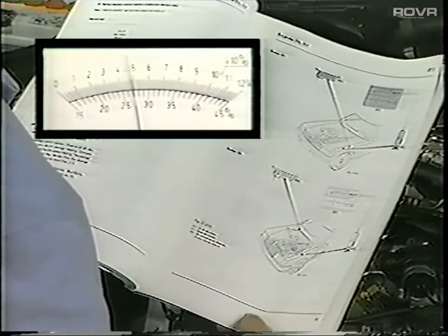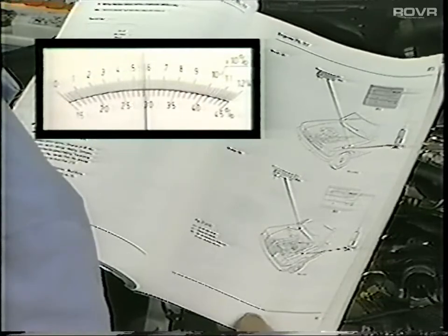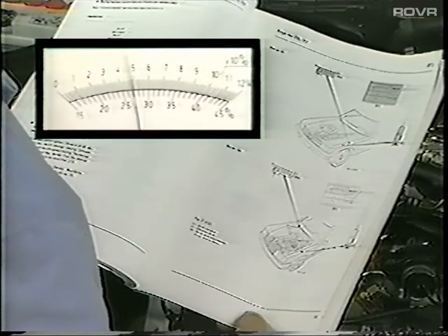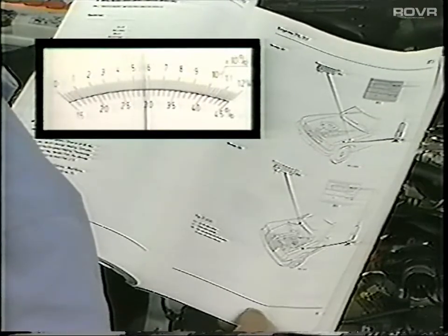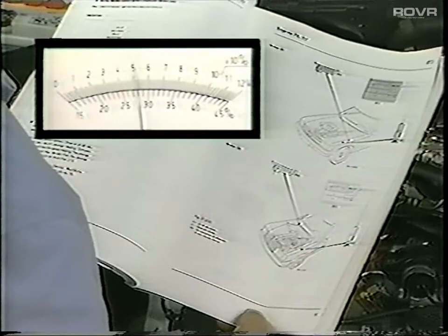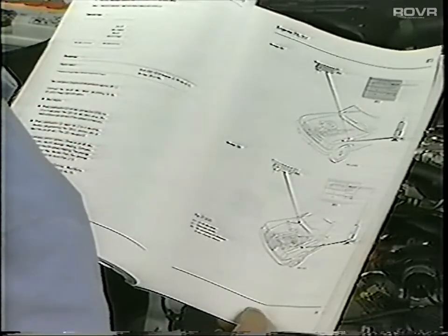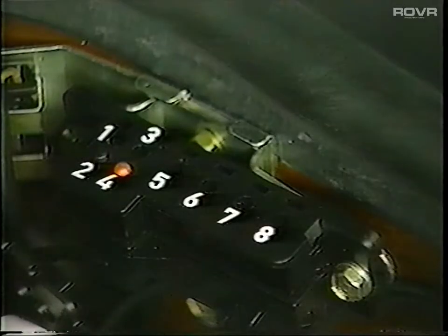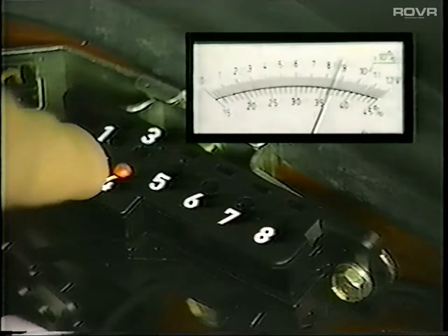The information in Test B is important since it explains the procedure now necessary to cancel the diagnostic signal and initiate the lambda frequency signal. This must be done before an on-off ratio reading can be taken. As noted in Test B, to cancel the diagnostic signal and initiate the lambda signal, you must first press the test button for 2 to 4 seconds.